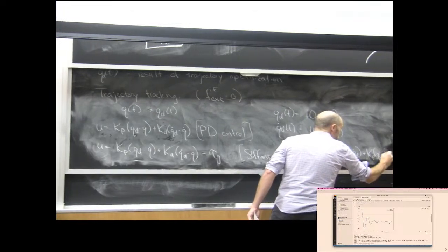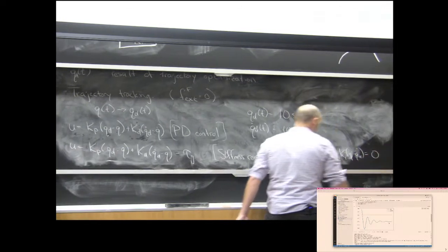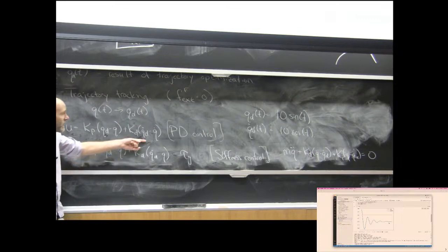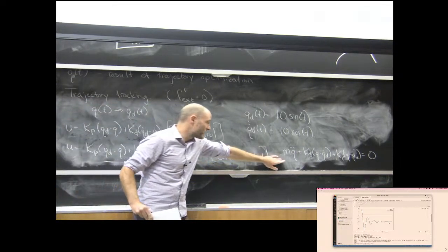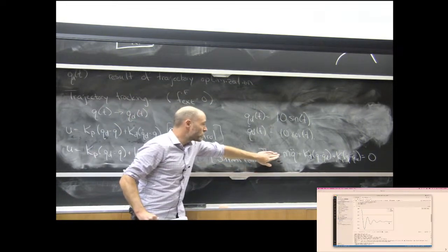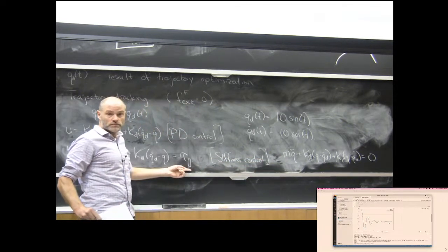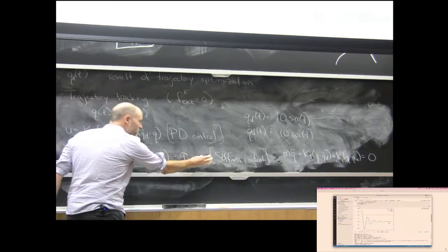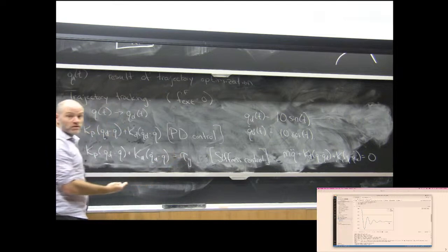Q desired equals 0, in fact, if there's no external force. Right? The PD controller has an extra nagging term from gravity. The stiffness controller, by virtue of trying to act like a spring, is actually canceling that out. But in the simple case, the only thing that's different between the stiffness controller and the PD controller is gravity compensation.